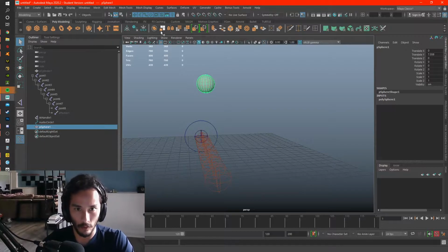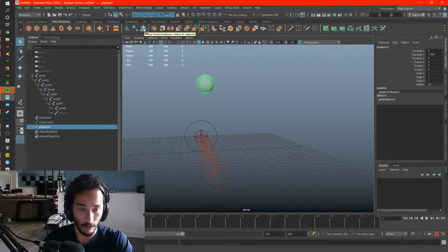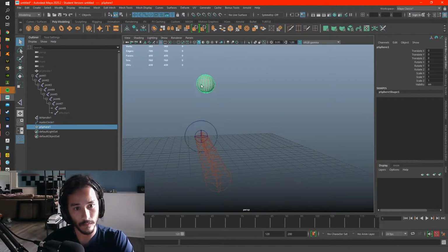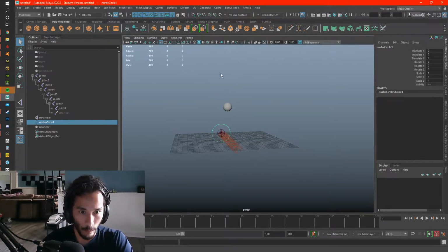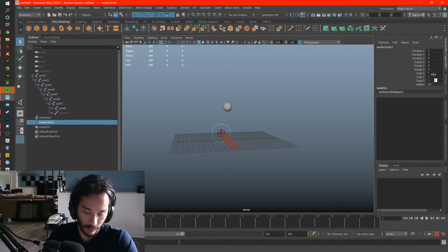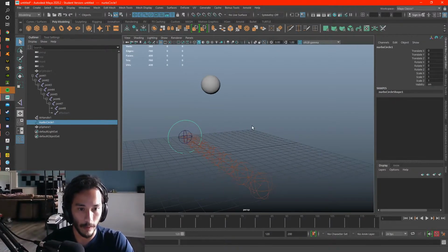And you want to make sure that all your curves, when you get to this stage in rigging, are frozen. This is something you would technically do after you've built your skeleton. You're going to make the control curves to control the skeleton. You want to make sure you freeze all your control curves, so that you'd be able to select all of them, and if you have your character in a whole pose, you can easily reset it by selecting all the curves and changing your translate and rotation values, and scale if you have any, to 0. And your character will go back into a pose or T pose.